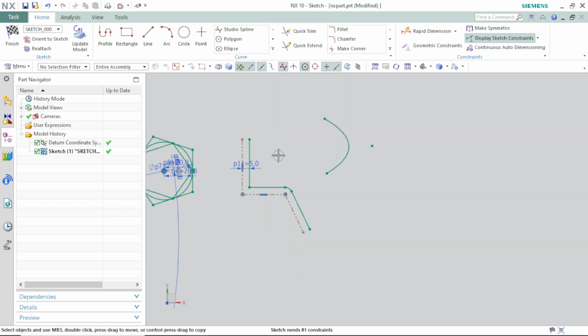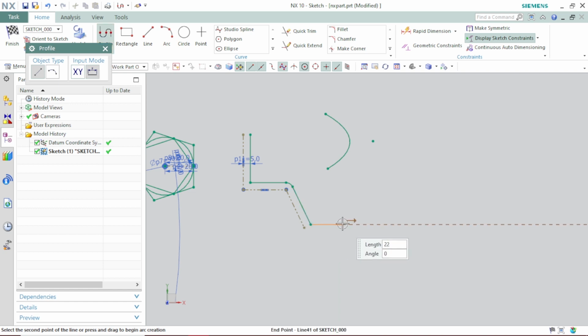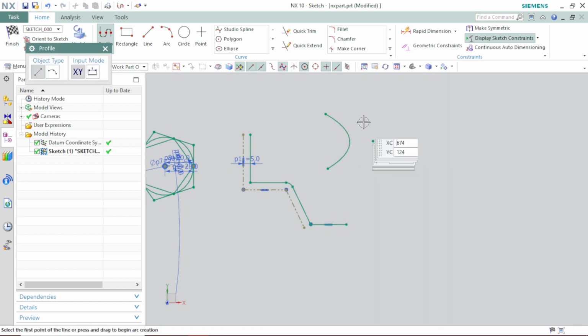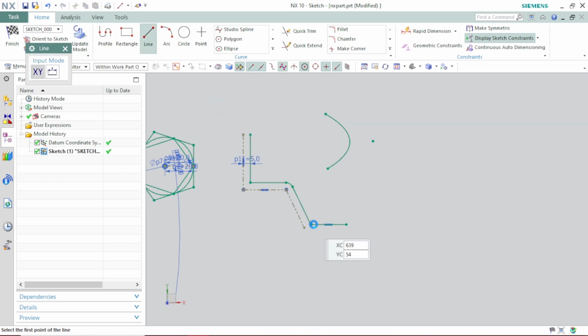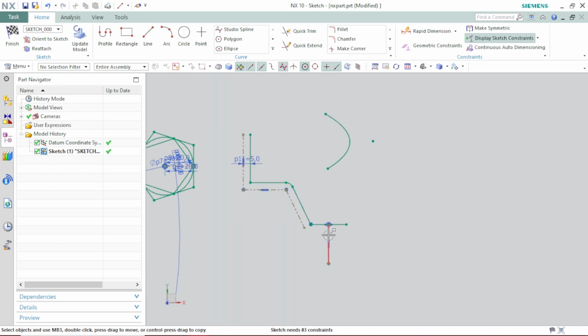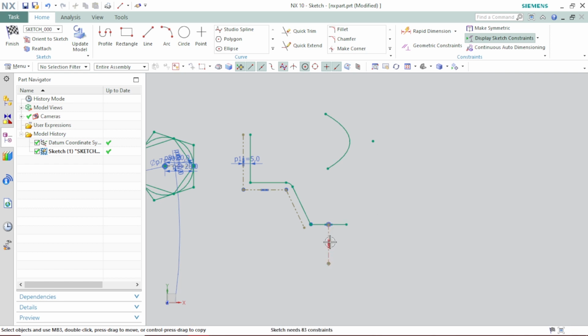When there is a sketch like here, the same sketch, you want on the right side also, just like the left side. If you want the same sketch to be here on the right side, you just need one line here, a mirror line between. Okay, just select this line, right click, and convert it to reference from here. So it will get converted into reference.